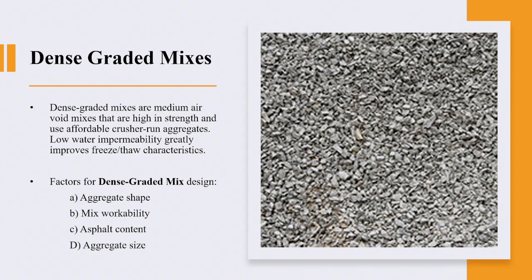The binder content, in the US I noticed we're slightly higher than most of the Gulf. Like in the Gulf they use 4.5, maximum 5. In the US 5 is about the minimum. Sometimes they go to 5.5 or even 6. There is about a 1% extra on the asphalt. Now there are pros and cons. You know, if you add more asphalt, maybe it's good for raveling because you have enough asphalt surrounding your aggregates. Maybe it could be good in fighting cracking.